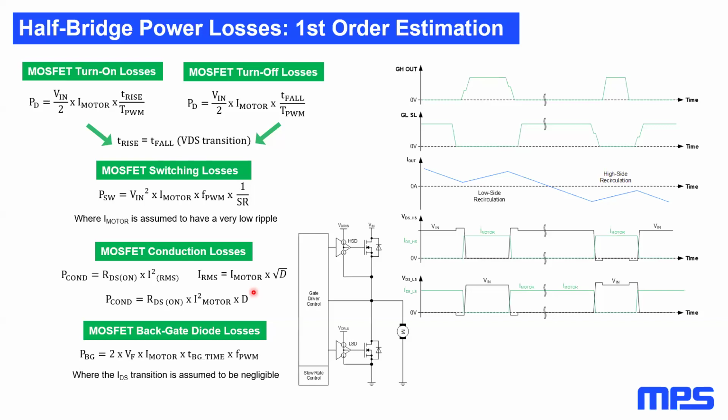And you start flowing 8 amps, 10 amps. Well, the formula is I squared R. So 10 amps squared is 100, times 20 milliohm resistance, or even 10 or 5. That gets to a number in the order of hundreds of milliwatts, or even 1 watt, like in our case.